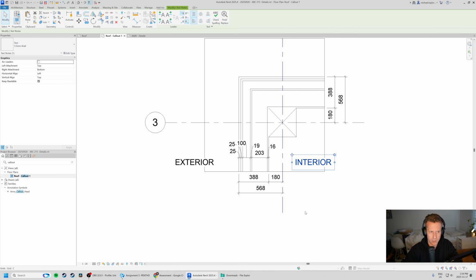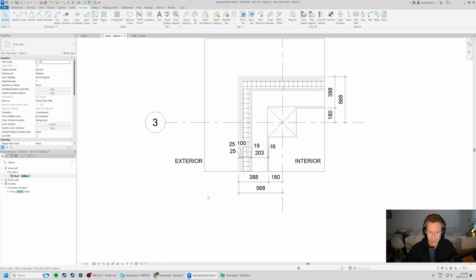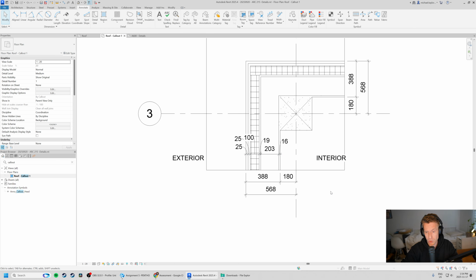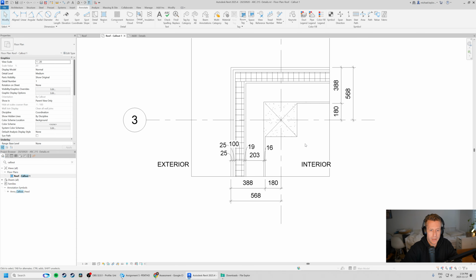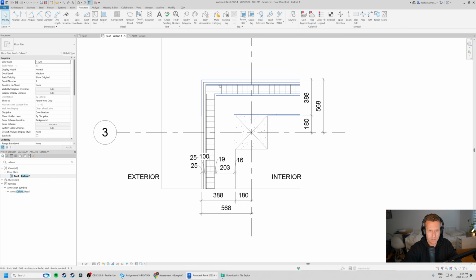Interior. For instance, right now these are looking pretty beefy, so one thing we can do is shrink the size of the text here. Can I make it 2.5? A little bit smaller. I would say 2.5. Whoops, 2.5 is a pretty good size for most offices. 2 is pretty small. 3 is probably you're erring on the maximum size when we're looking at details. But every office has their own graphic standards, and I'm just trying to get us to the finish line here.